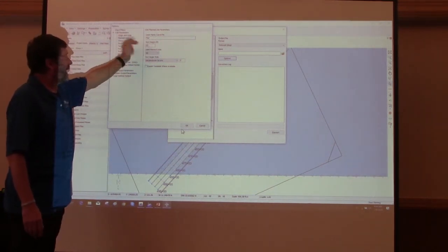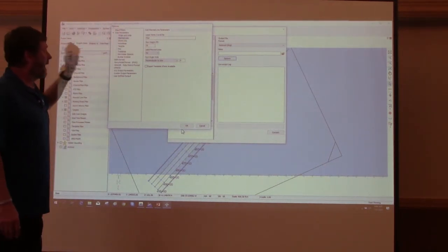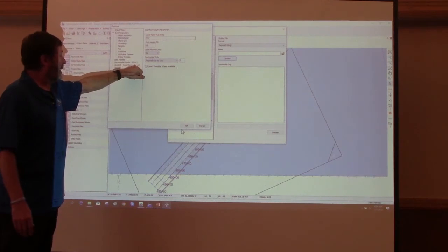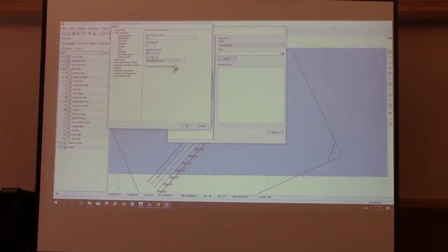Yeah, you can enter your text height here, and that's in real world units, CAD units. Whether or not you want to label the plan lines, and also you have your text angle style: perpendicular to plan line, parallel to line, or also at a fixed angle. Okay. Shoreline here, it's going to take your CAD files, your background files or contours, and put them on a specific level. And I think now, if you have multiple CAD files, it's going to just create additional levels automatically.